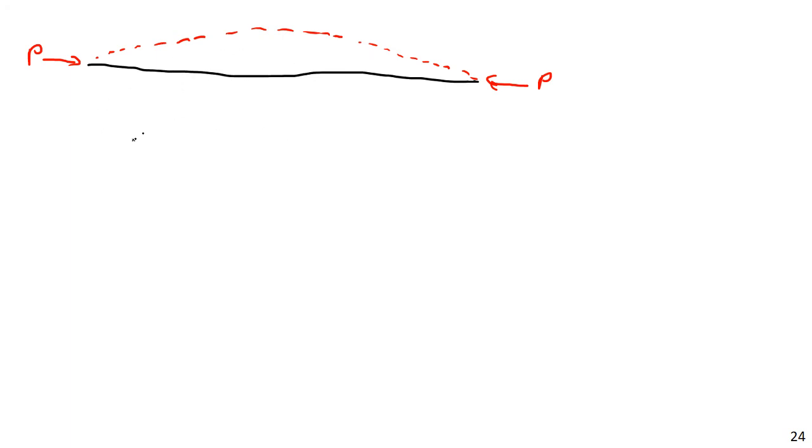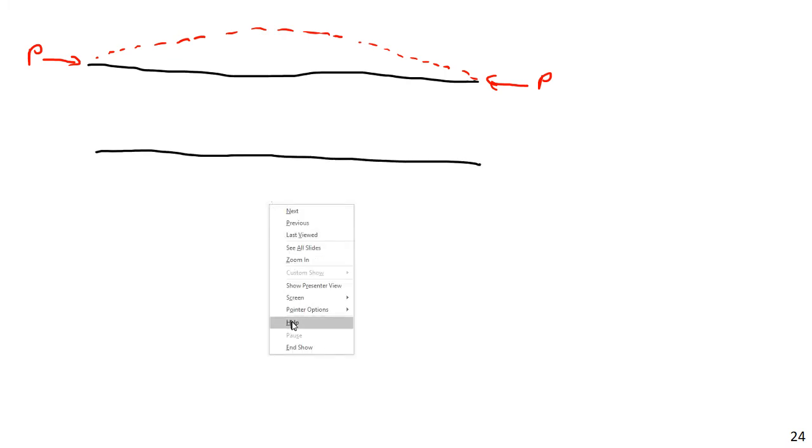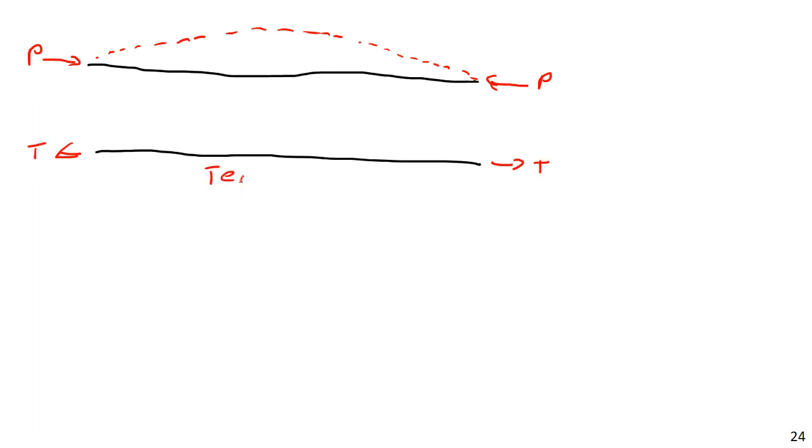You can't cause a tension member to fail by buckling. The only way to get a tension member to fail is by making it yield, or fracture, or by block shear or something like that. Tension members cannot fail in buckling.